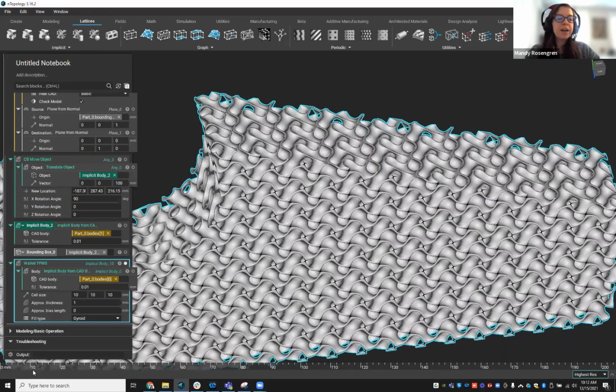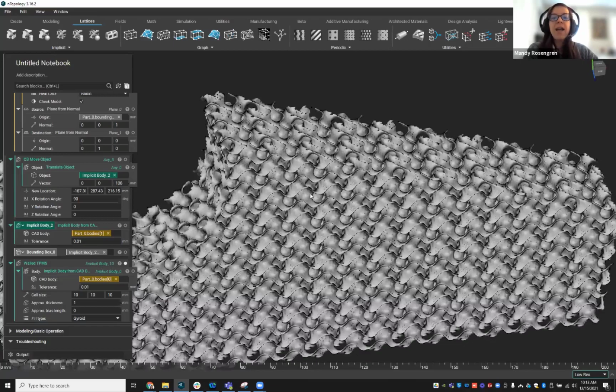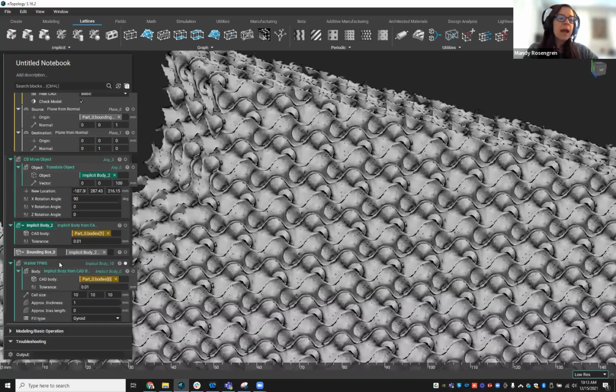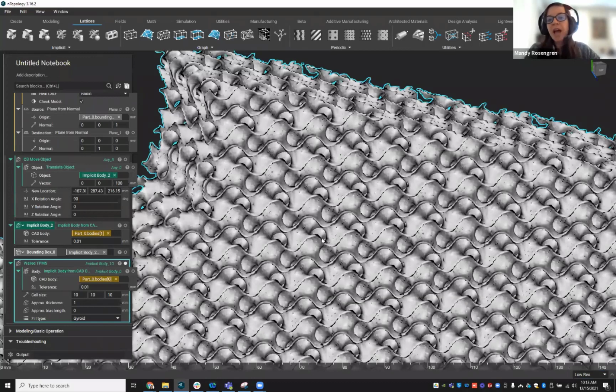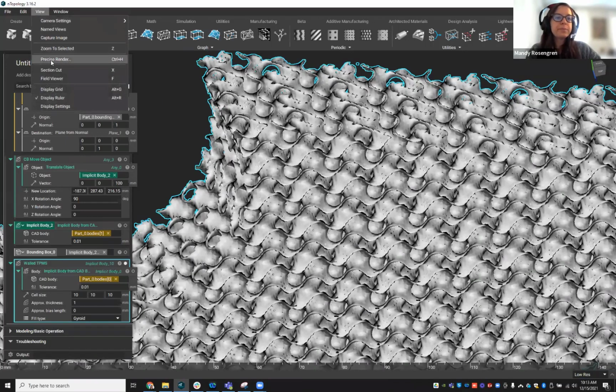If I look at the bottom left of my screen, that shows how long it takes to run. With our highest resolution, it will take a little longer to run because you're going through everything in that resolution. Another way to do a sanity check is to select the block you want to double check, visualize, or maybe take a picture of to send to a colleague. You can go to view, and as well as that highest resolution, we have this precise render. Even if the highest resolution shows some issues, our precise render is an even better check.